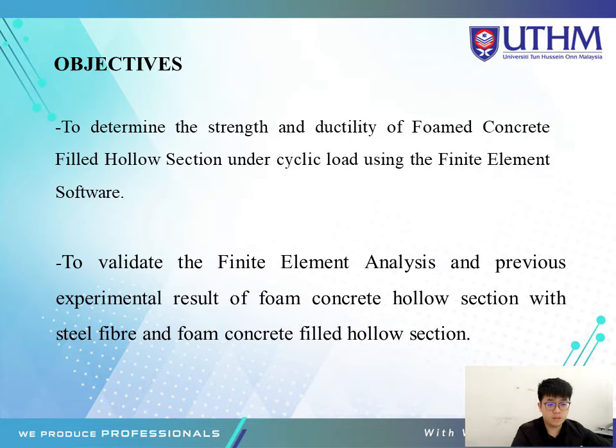For the objectives, the first objective is to determine the strength and ductility of formed concrete filled hollow section under cyclic load by using finite element software. Second is to validate the finite element analysis against the previous experimental result. For the scope of study, this research is to identify the values obtained by using the finite element method in terms of ductility and resistance ratio of concrete filled hollow section using formed concrete with the addition of steel fiber, while comparing to the experimental result of the previous study. To achieve the objective of this research, the experimental result carried out by Ahmad Luqman is used as the reference.